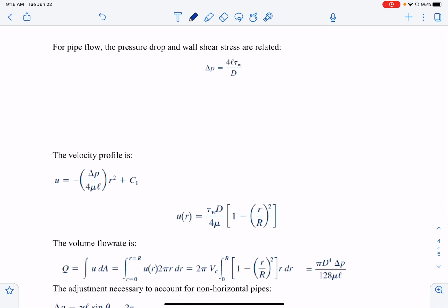here, right? And then also what we have from the other chapter, we know that tau is equal to minus viscosity times du by dr, right? And if I just cross multiply that one, so tau is going to be del P r over 2L. So now this is tau and this is tau.